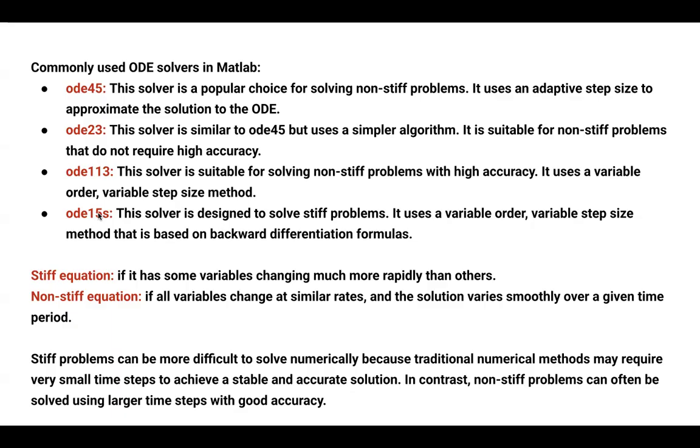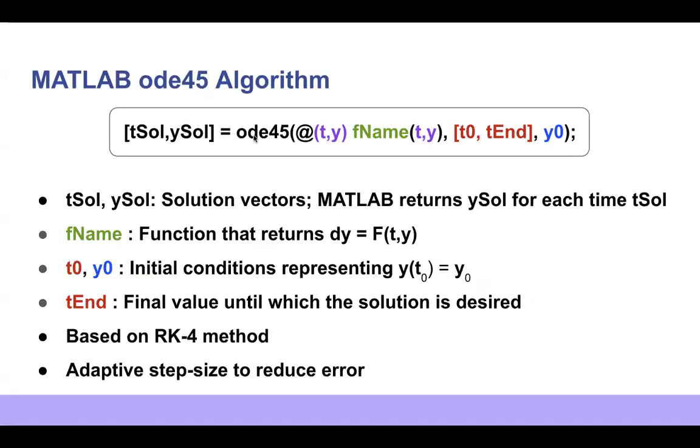Apart from this, there are other ODE solvers also. You can just Google MATLAB ODE solvers. You'll get a list of ODE solvers and also get to know where and why they are used. How to use them is pretty simple. All the solvers have the same syntax. If I want to use ODE15s, I go back to this equation and instead of ODE45, just write ODE15s. The syntax remains the same. You just have to use the appropriate ODE solver depending upon the difficulty of your problem.